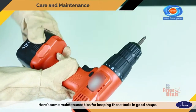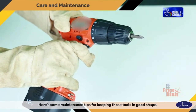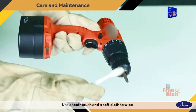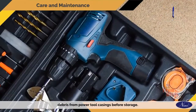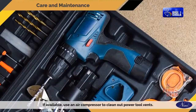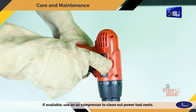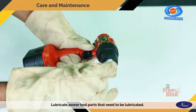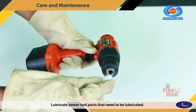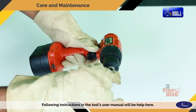Here are some maintenance tips for keeping those tools in good shape. Use a toothbrush and a soft cloth to wipe debris from power tool casings before storage. If available, use an air compressor to clean out power tool vents. Lubricate power tool parts that need to be lubricated. Following instructions in the tool's user manual will be helpful here.